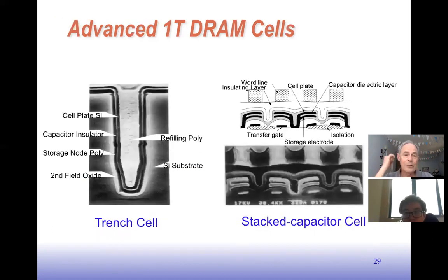Now, I just wanted to mention something about the processing. I said that DRAM chips use a special process. Therefore, we don't see DRAM blocks of 1T cells very often on logic chips like microprocessors. The large memory blocks on processors and other large chips will use SRAM, because having special processing steps just for the DRAM would make them more expensive. It is possible, and there are companies that make so-called embedded DRAM, which has some special processing steps for making large memory blocks, but it does increase the price, so it's not so popular.